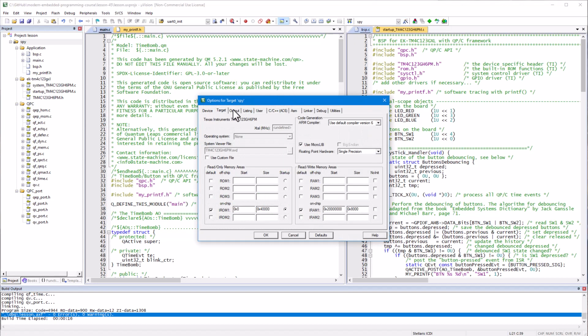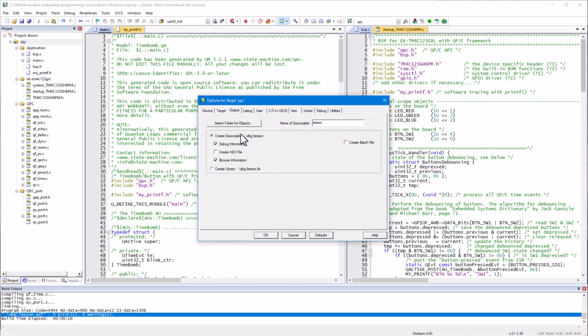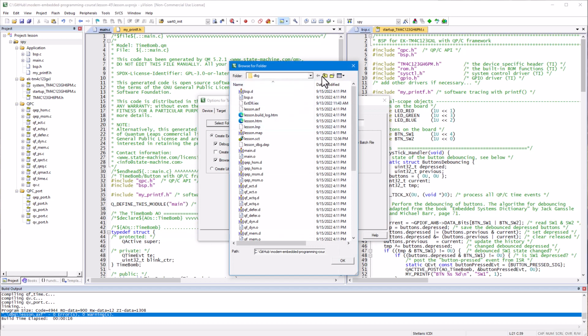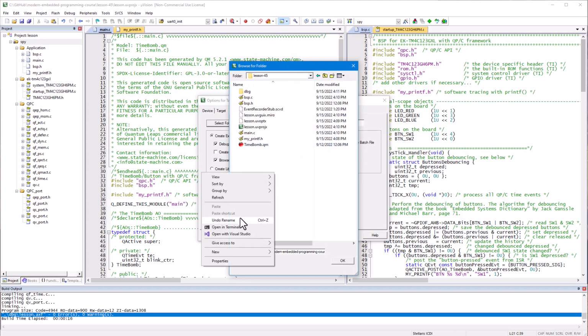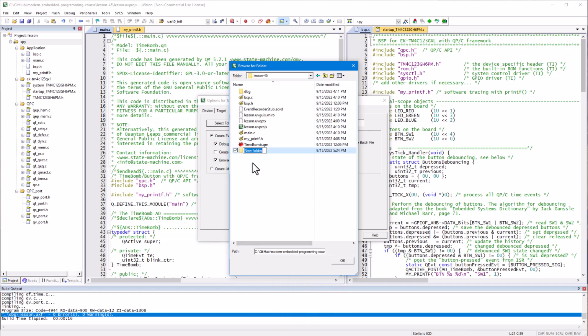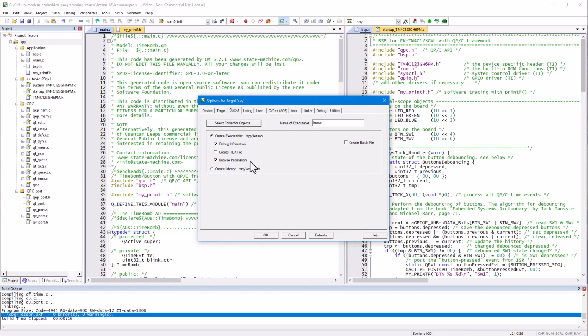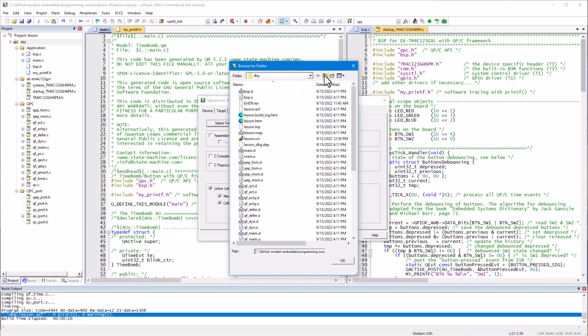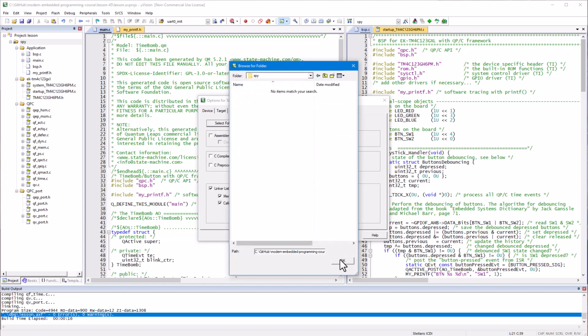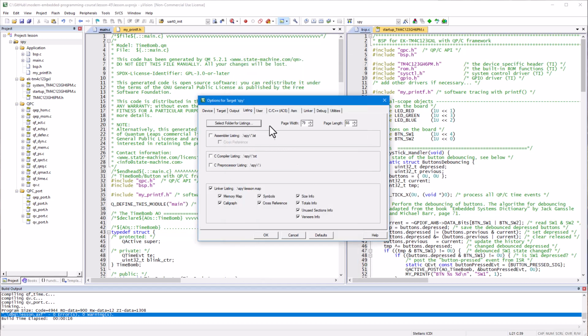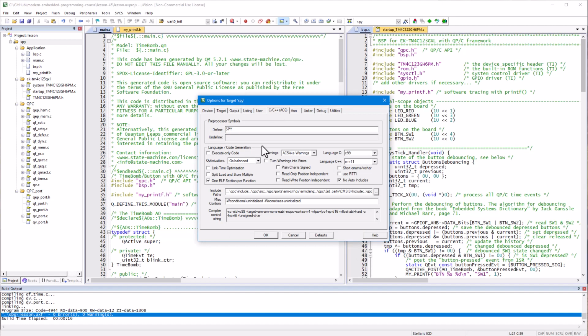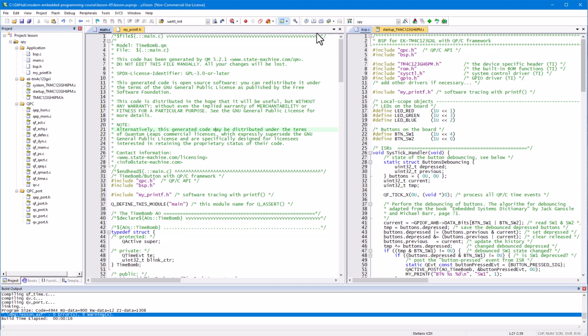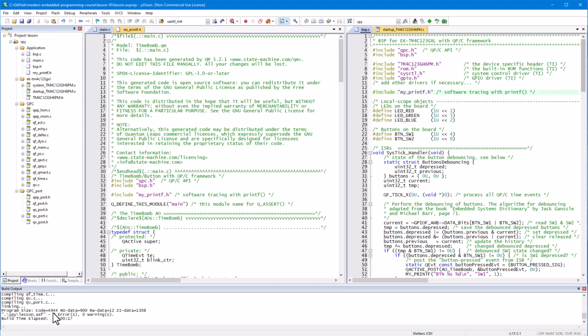In the Output tab, you still have the DBG folders inherited from the DBG configuration. You need to change it to the SPY folder, which you create on disk. A similar situation occurs in the Listing tab, but this time you just use the already created SPY folder. In the compiler settings, you obviously keep the SPY macro definition because it enables the tracing instrumentation in the code. Now you can finally build your SPY configuration.